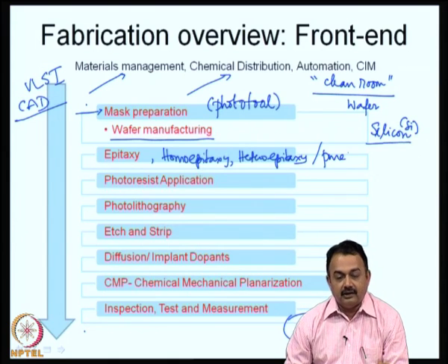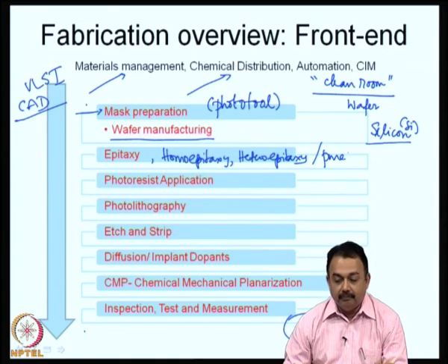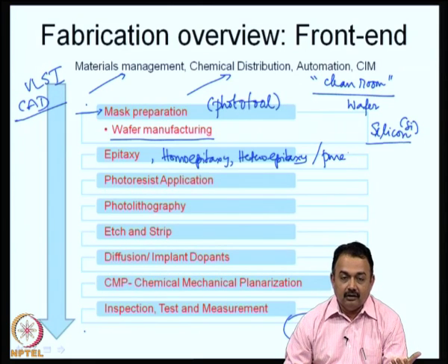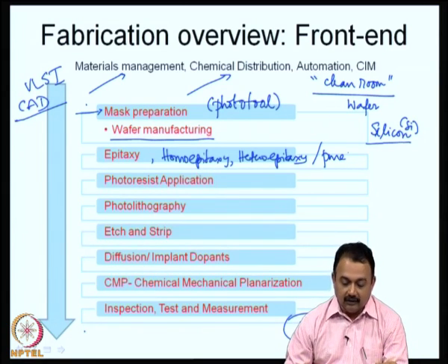So, after epitaxy there will be an oxidation process. So, to get a good conversion of silicon to silicon oxide, we do an epitaxy process to get a pure monocrystalline film on the wafer. So, the wafer is initially well cleaned, okay, so that it is free from any of the impurities. Remember, the starting point and the end point, the entire process is done in a clean room. So, I will talk about clean room requirements very shortly.